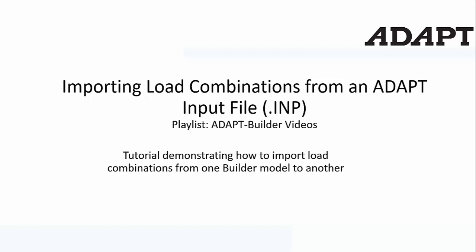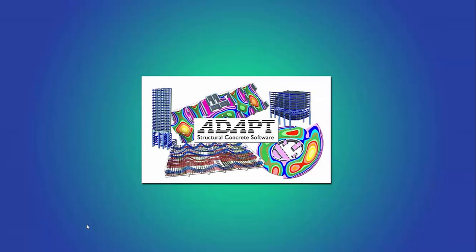In this video tutorial, we're going to talk about how to import load combinations from one Adapt Builder file to another Adapt Builder file using the .imp format. And this is mainly used to save time so that the user doesn't have to re-enter load combinations when we have several that need to be processed for a model. We'll go ahead and get started now.